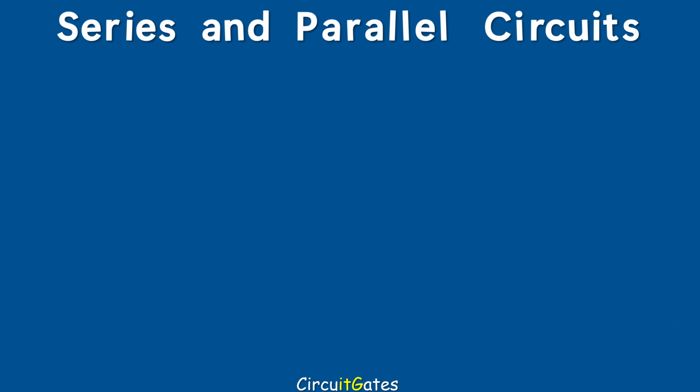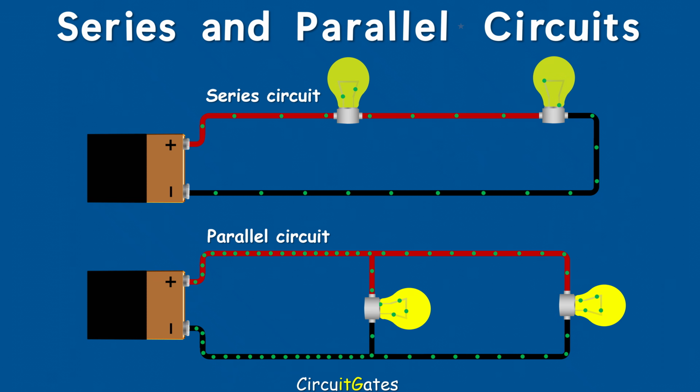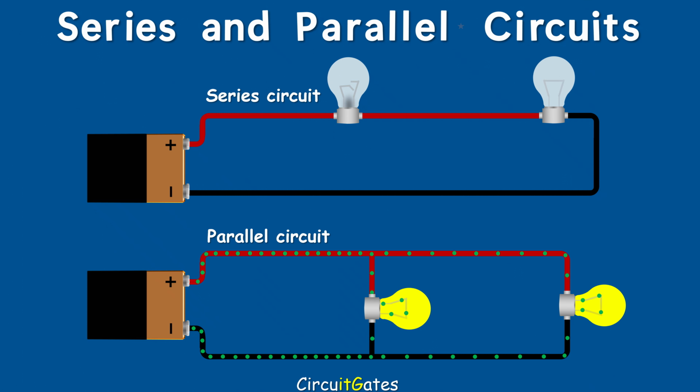There are advantages and disadvantages of connecting components in series or in parallel. In a series connection, if one component stops working, the other components will power off. This is because components are connected in the same path. Current is following a single path where all components are connected. So if one stops working, it causes the circuit to be open, while current flows only in a closed circuit, thus stopping current from flowing and causing other components to power off.